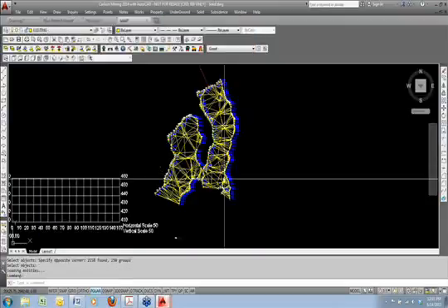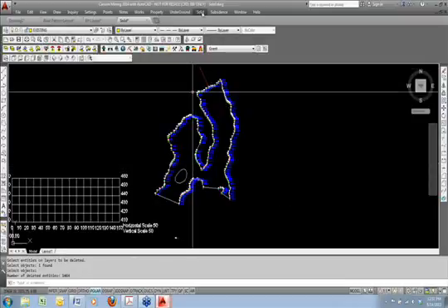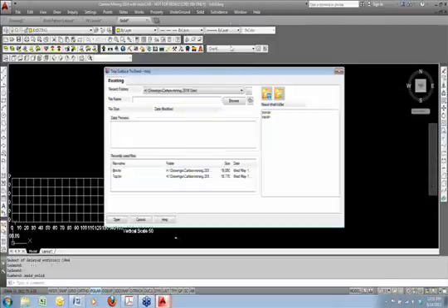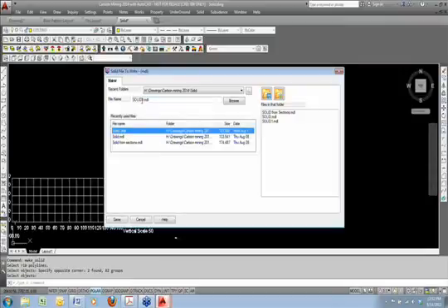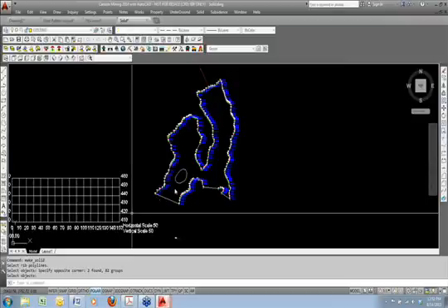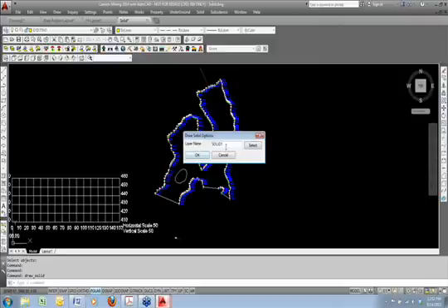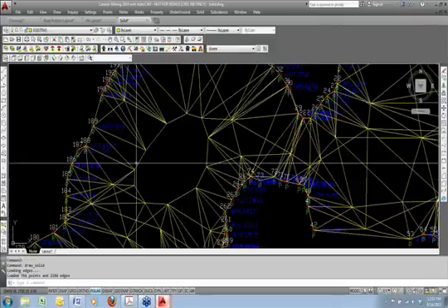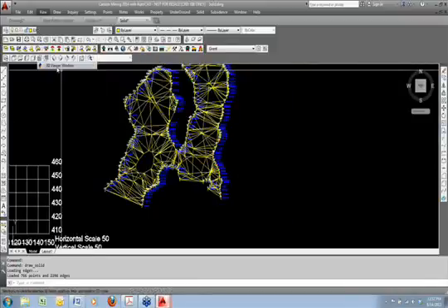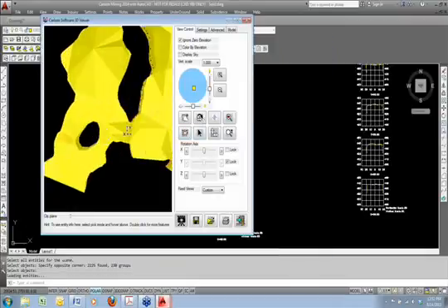All right, so let's go ahead and erase that. I'll just delete layer, and then I'll run it again, solid from surfaces, choose the top, and then the bottom, and then I'll choose both of those polylines. And I'll call this one solid 2. That'll have the exclusion. And then we'll draw it, and you should see, we'll call it solid 2, the opening, like so. And then we'll just take a look at that in 3D with the 3D viewer window. So these are just 3D faces, triangulations, and there it is.